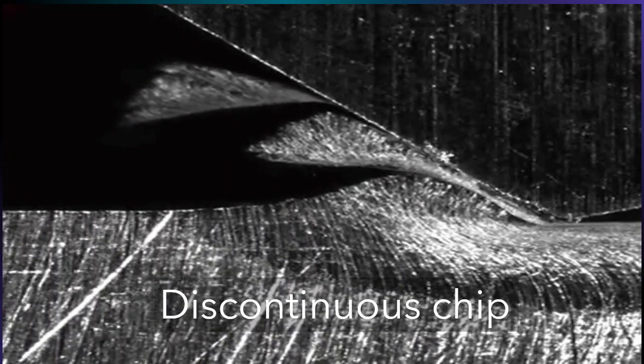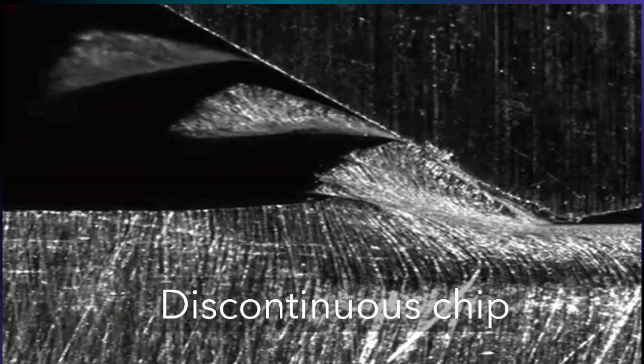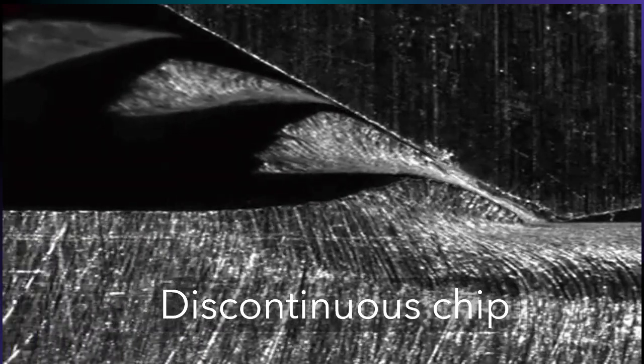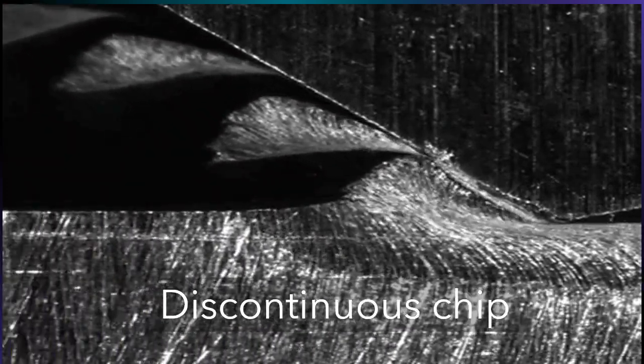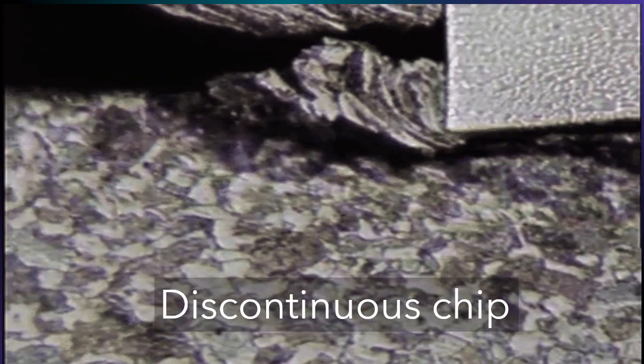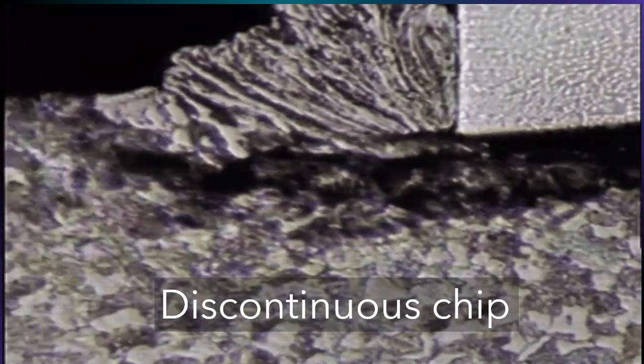The chips often form into separate segments. This tends to impart an irregular texture to the machined surface. High tool-chip friction and a large feed and depth of cut will promote the formation of this chip type.